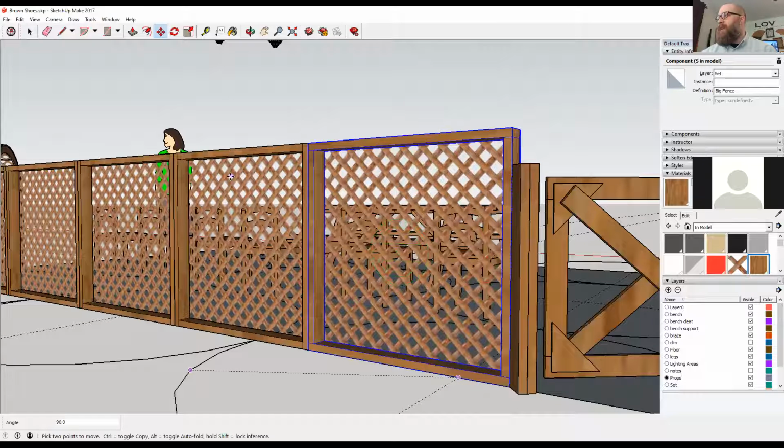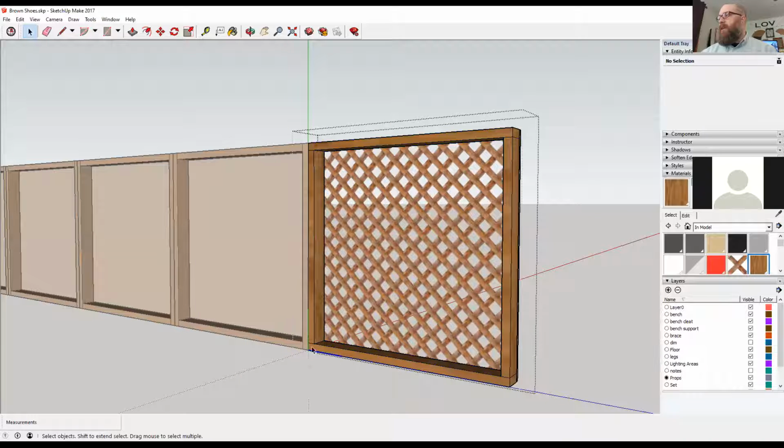Like that. The advantage that serves is then when you're moving the piece of scenery, you don't have a seam at the floor that can get snagged on things and pulled apart. And again, that's the sort of thing that you just sort of learn over time, and then once you learn it, you remember it. And there are times where you would do it the other way.